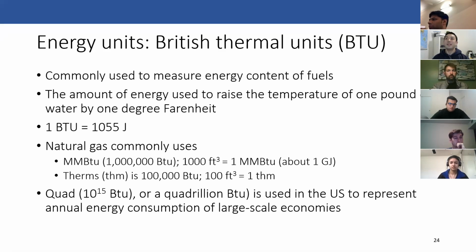So it's really common, for example, to have some kind of number for the heat rate, and then it'll be in units of MMBTU per megawatt hour or per gigawatt hour. And that tells you directly how much electricity can I get out of some amount of fuel input, right?